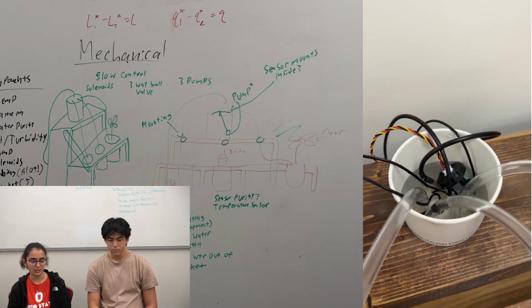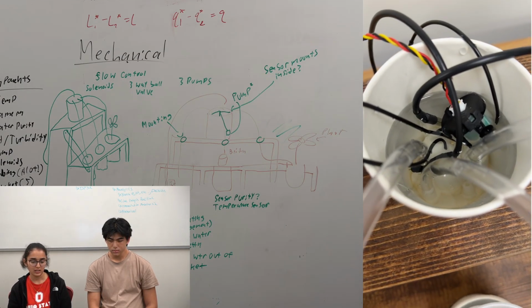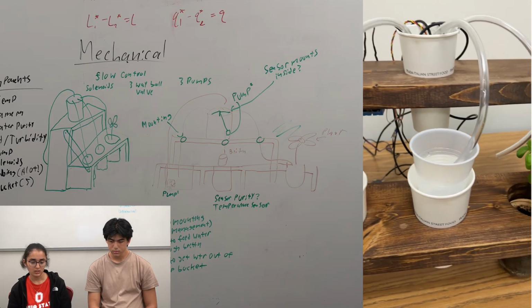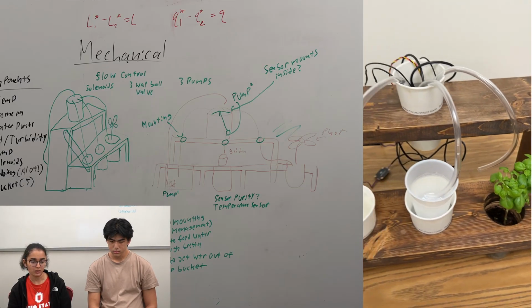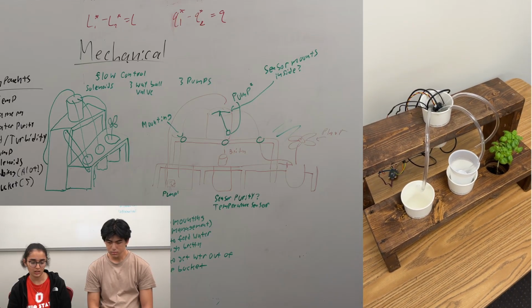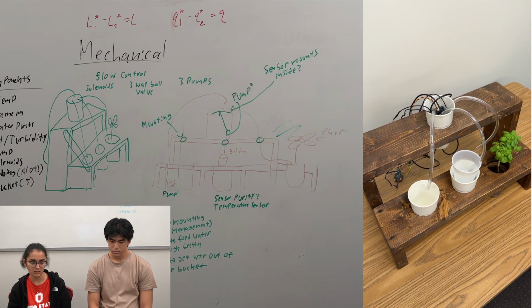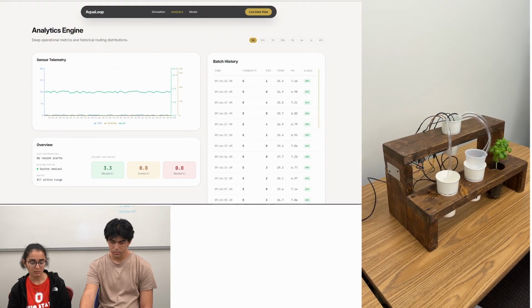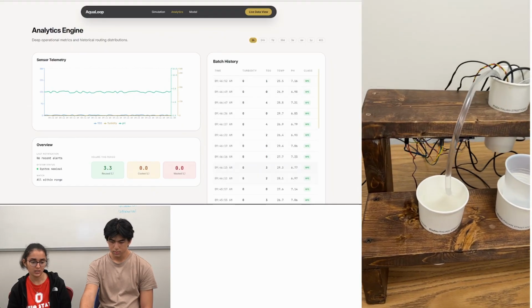This is our sensing tank. Down in the water we have got turbidity and TDS sensors and probes for temperature and pH. Downstream we have got 3 outlets we can open based on the output from a fine-tuned ML model that was trained to have 92.8% accuracy. We start with distilled water. Right now the system thinks this batch is at minimum, which is good enough for high-grade reuse, so the reuse